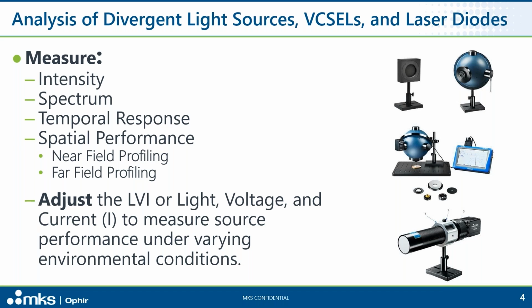Temporal response. This is the time-based optical output for a given electric input. Important issues include on-off times, overshoot, undershoot, minimum pulse width, and energy efficiency, or energy in for usable energy out. Spatial performance. This indicates how the light propagates or shines out. Spatial performance, or laser mode, is important as it may limit how the light can be effectively applied and dictates how the light should be collected for use.